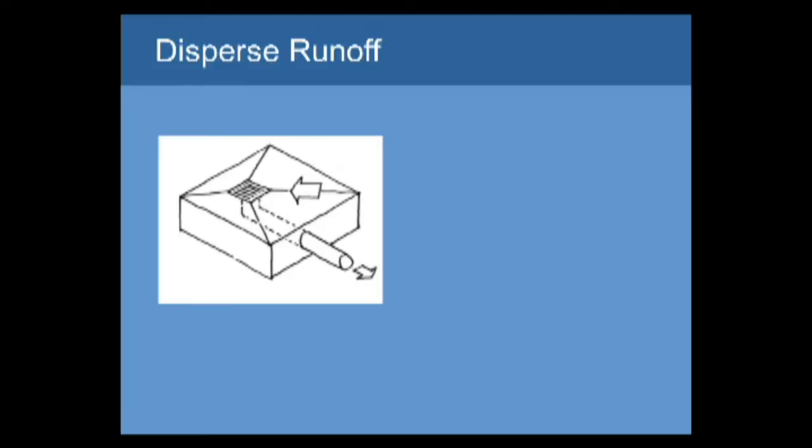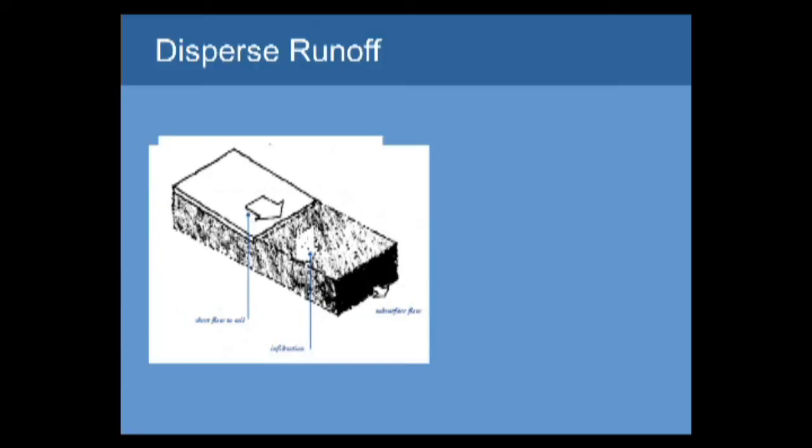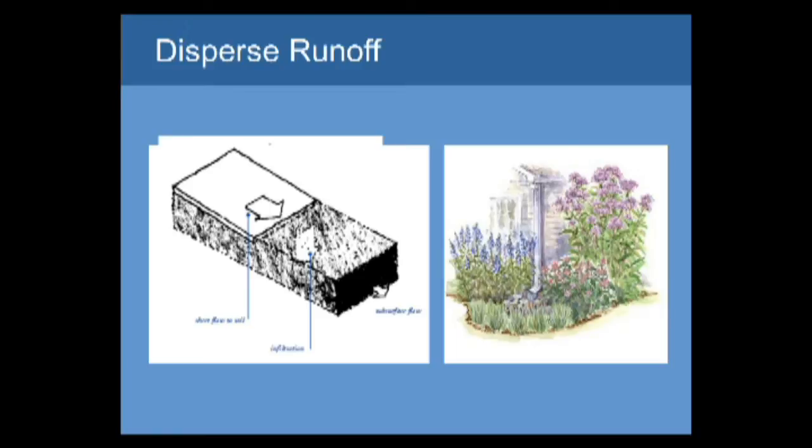What is productive is getting people to disperse runoff and to go from this collect and convey concept to what I've heard described as a back to the future concept, the way that we used to do things, of simply trying to disperse runoff off of our driveways and roads and parking lots, and push it off into the bushes, into the landscaping. By far the most sustainable, cheapest, best way of doing things. And one of the things that we've been working with the board on even now is figuring out how we can ensure that that is properly credited with the limits that they want on it, and we'll get into that later.